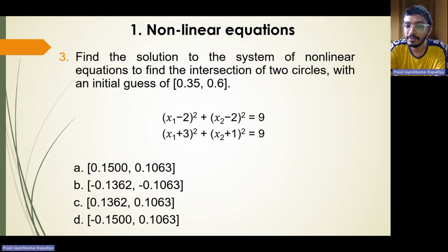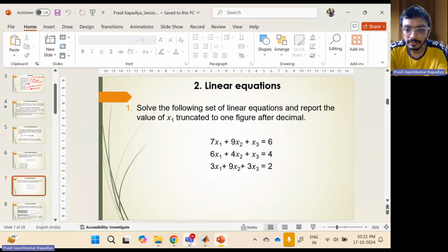And when we have a polynomial kind of equation, we can also use the roots MATLAB inbuilt command. So these three things we learned. Then we further checked how to solve a system of equations like coupled equations. These two are coupled equations and we need to solve them simultaneously. So this is what we also learned, and we solved it using the fsolve MATLAB command.